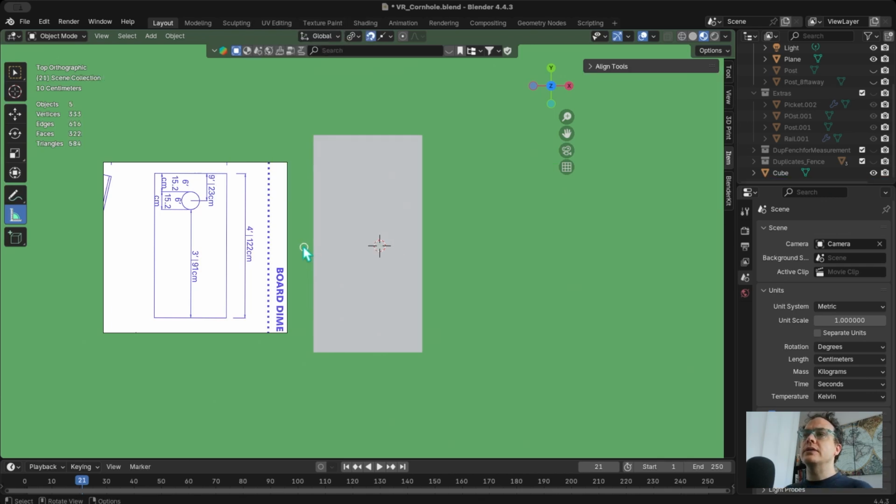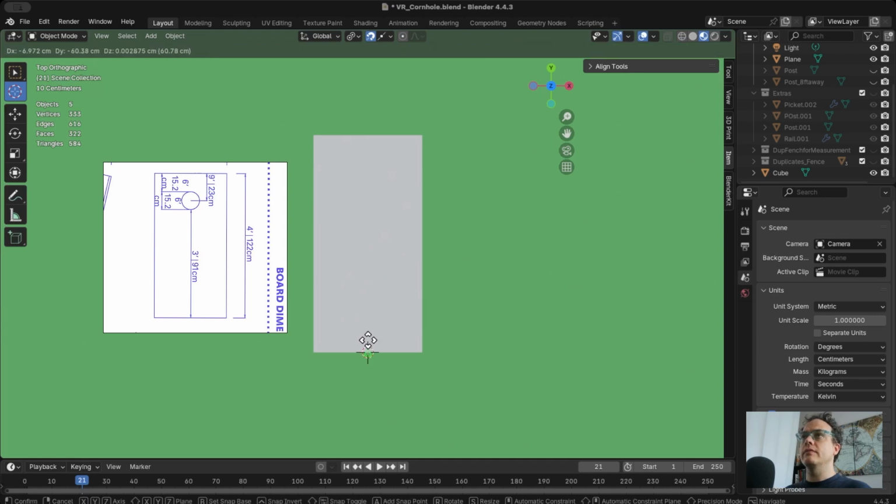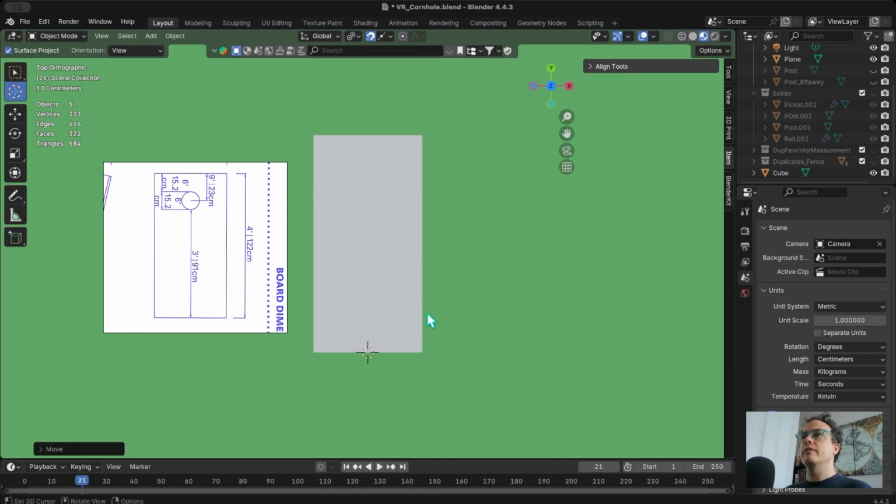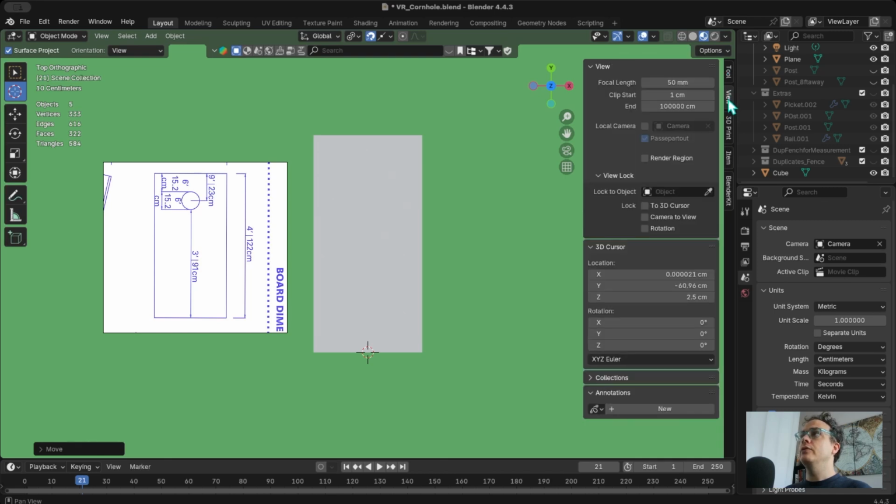The best way to do this is all about the 3D cursor. With our snap to the edge center selected, we're going to left click this. There we go, we've got a perfect snap there. Then we bring up the side panel on the View tab and twirl down the 3D cursor. All we have to do here is enter whatever distance we're trying to go. For myself, it's along the Y axis here according to my diagram.